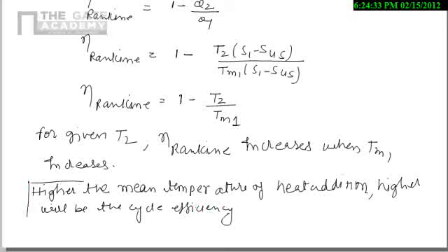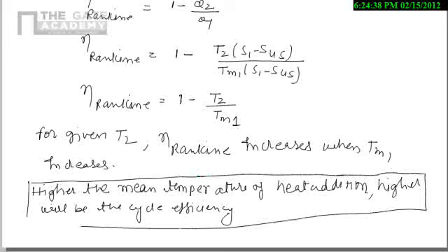So remember this thing, this is very important. If the mean temperature of heat addition is increasing, then the Rankine efficiency will also increase.